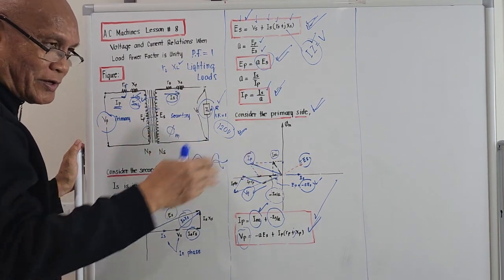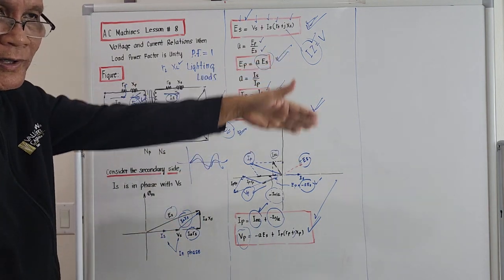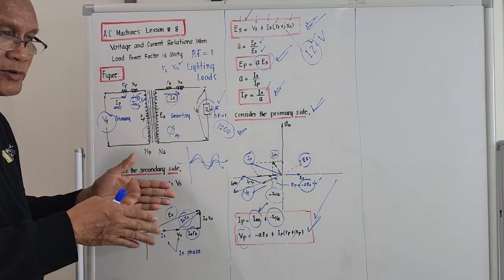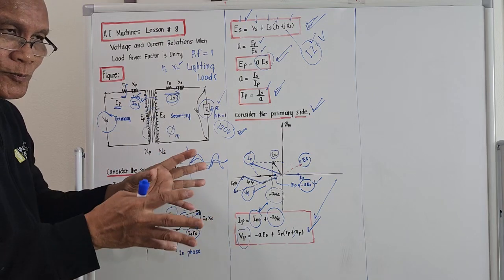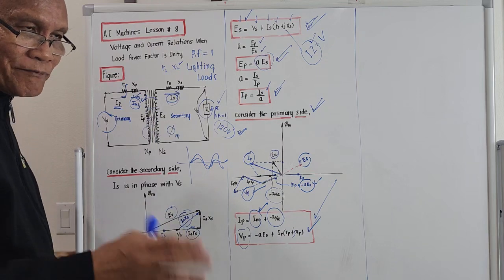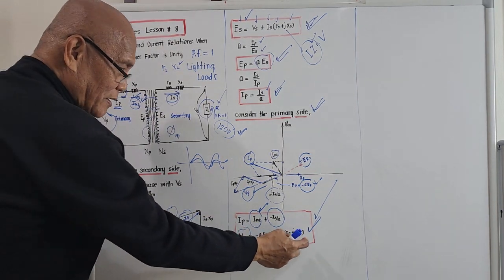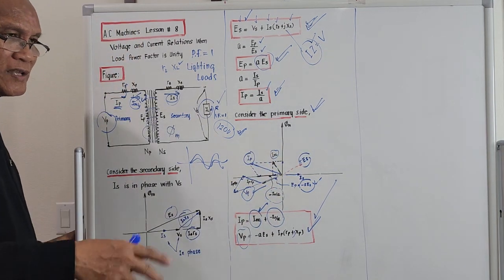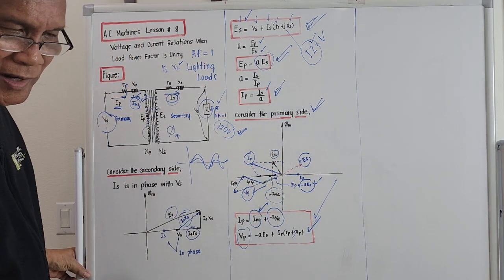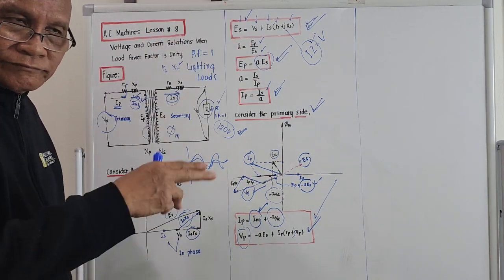Because without considering it, the voltage that will be appearing at the far end, we could not predict the value. So to predict the value, you take into consideration the effect of the so-called resistance and inductance. And there's another thing for these transmission lines, the so-called capacitance effect to ground.